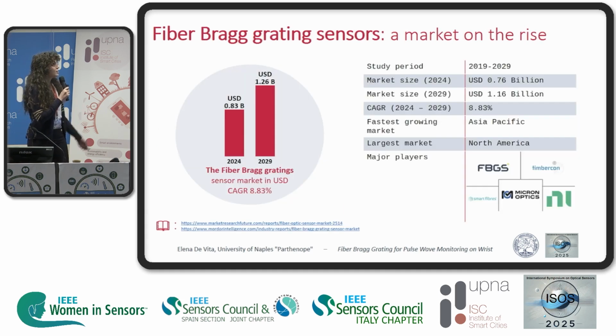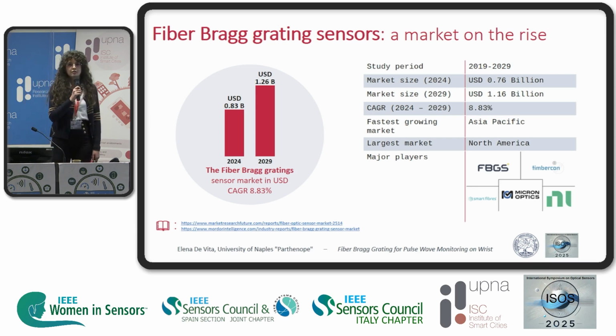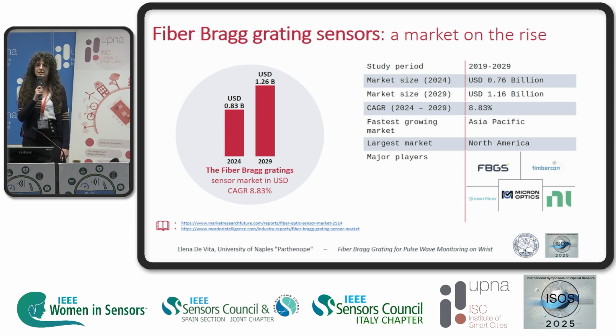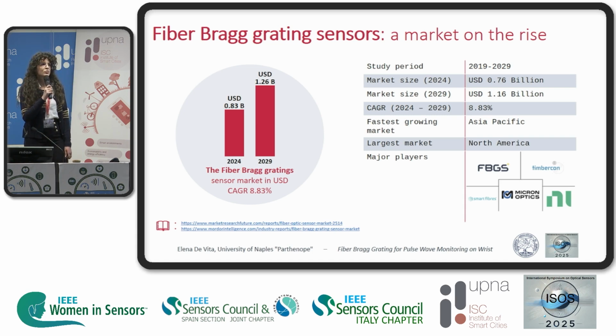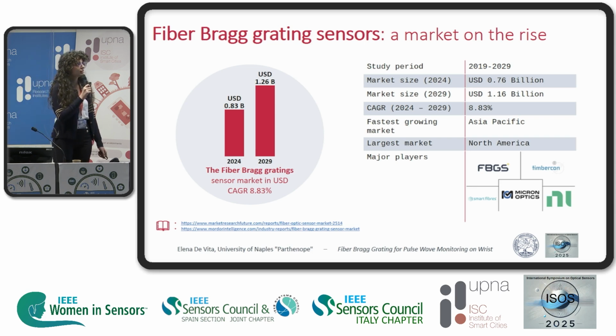But among all the fiber optic sensors, fiber Bragg gratings, FBGs, are becoming a popular solution, especially for the measurements of temperature and strain, but not only, because of their advantages, features, like the wavelength encoded nature of the output, for example, but also the relatively low cost, the longer lifetime with respect to other sensors, the great flexibility of design, and many others.